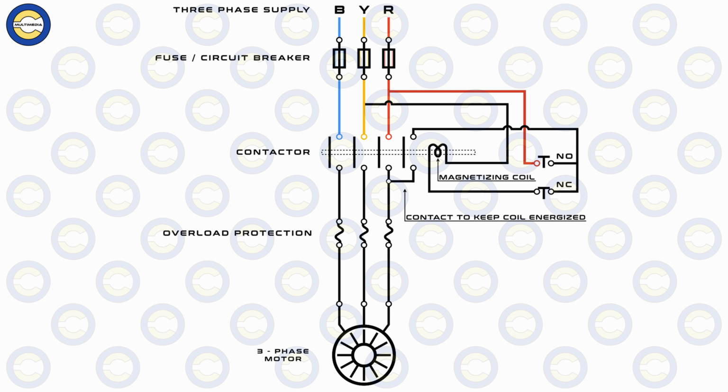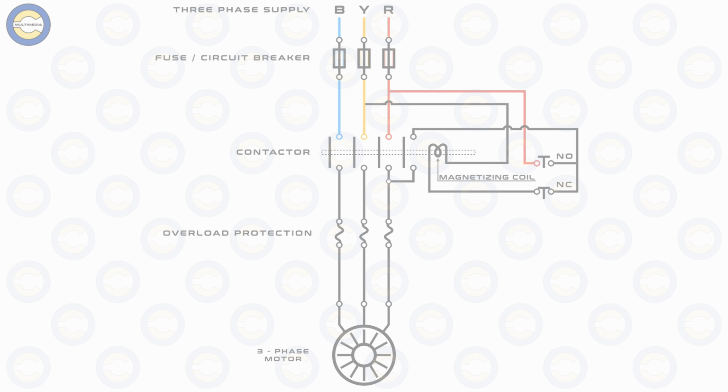As we will see later in our other videos, the larger motors used on board, for example the heavier or main seawater pumps, the main air compressors, the winches or any other, for example the ballast pumps, will use star delta starters or auto transformer starters instead, which are other variations of the electrical starters used for starting and operation of motors. I hope that you have found this explanation helpful along with the diagram and the animation.